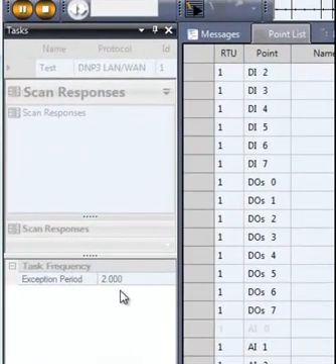The application period, that is, how often the increment value is applied, is set in the exception field in the RTU simulation task. The default is 2 seconds. The increment is applied whenever the exception period expires, as long as any previously incremented values have been transmitted.